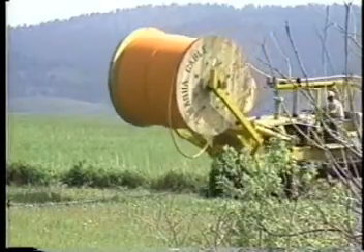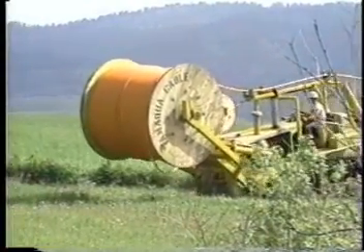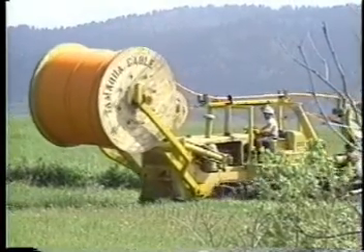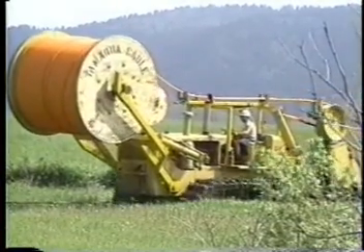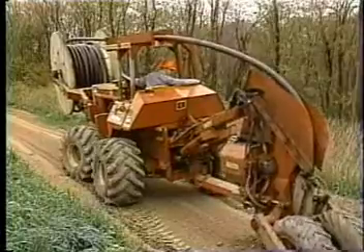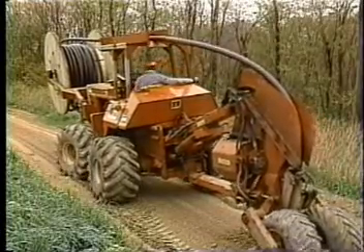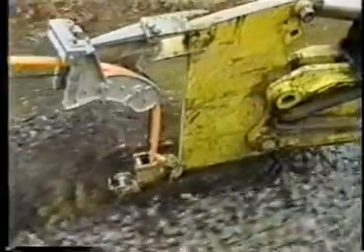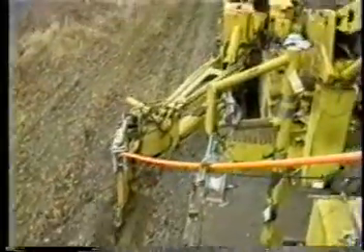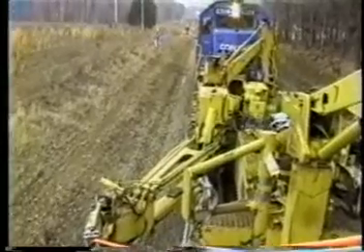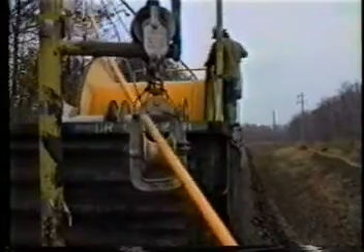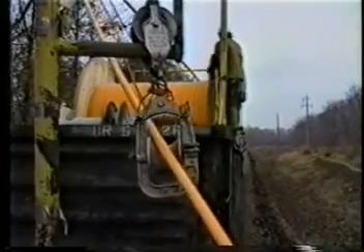Duct, fiber optic cable, or cable in conduit can be placed underground by cable plows for long-haul applications. Standard plowing equipment is most often used, but modifications may be required to meet the cable manufacturer's specifications. Plows can be mounted on rail cars when installing cable along existing rail right-of-ways. This also provides a convenient method of transporting additional cable reels.